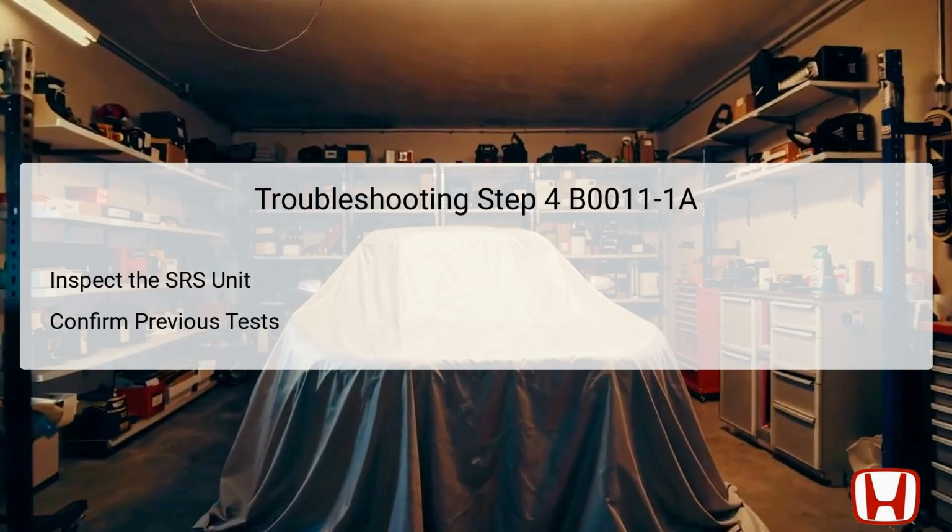If both components check out, yet DTC B0011-1A remains, the SRS unit is likely the source of the problem. This unit processes signals from other components, and if it malfunctions, it might incorrectly signal that there is an issue elsewhere. By determining the condition of the SRS unit at this stage, you can confirm whether it requires replacement or repair. Always ensure you have performed thorough testing of the associated components to avoid unnecessary replacements.